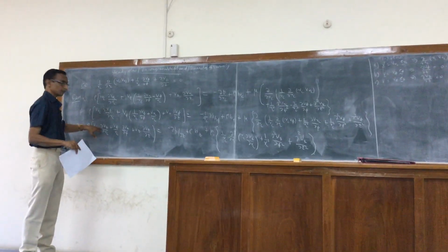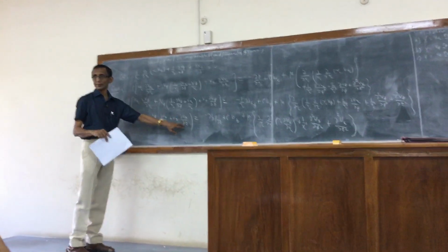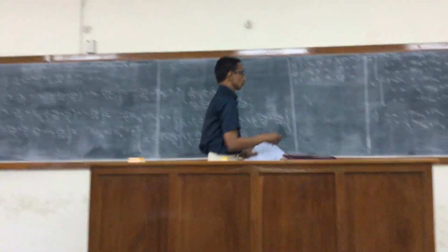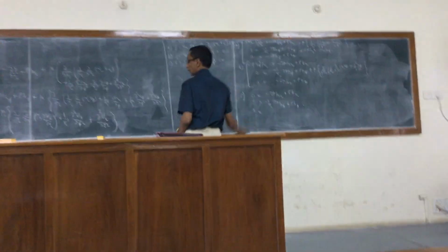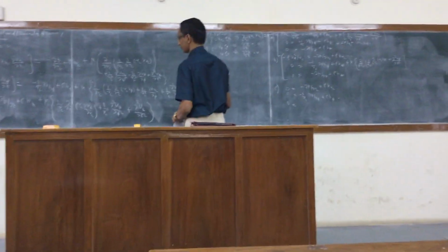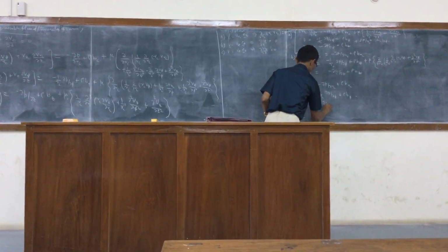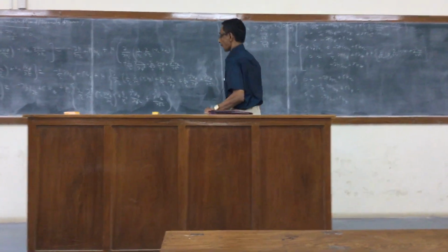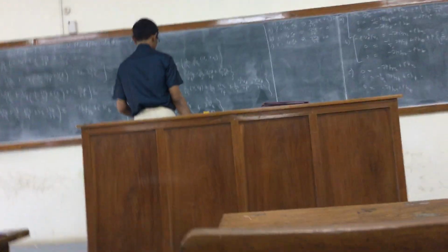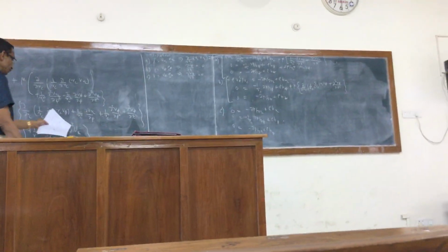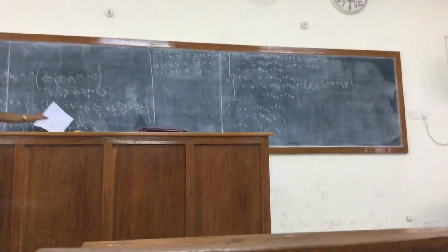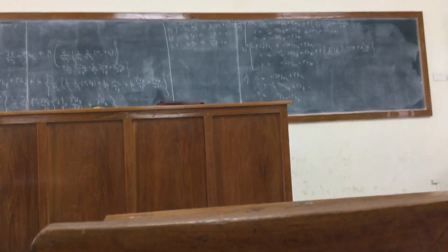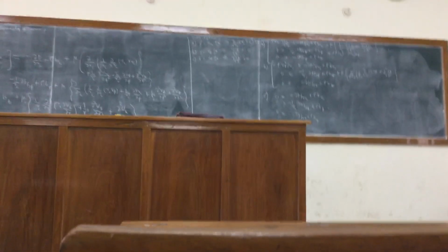Again, the inertial terms are 0 because dVz by dz is 0 by the continuity equation. The inertial terms are 0, and then obviously I will have the viscous term, so minus dp by dz plus mu times d squared Vz by dz squared. dVz by dz is 0. So Vz is independent of z, that's what it means. Because these are identical relations, valid at all points, Vz is independent of z.